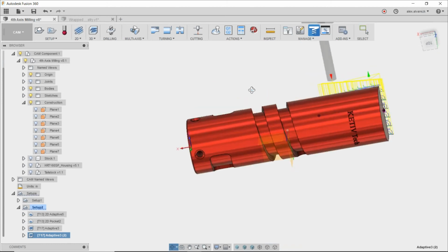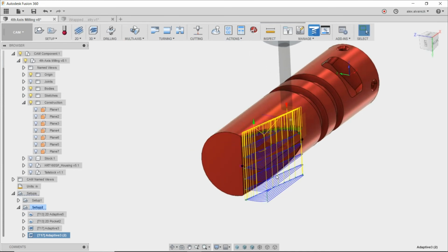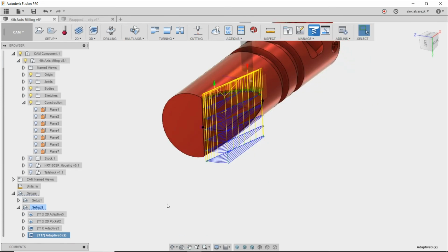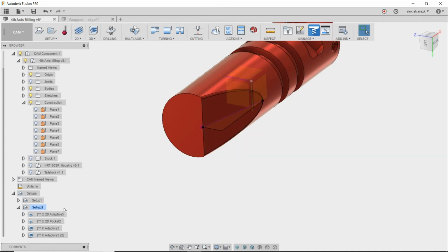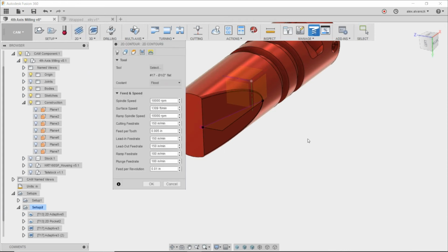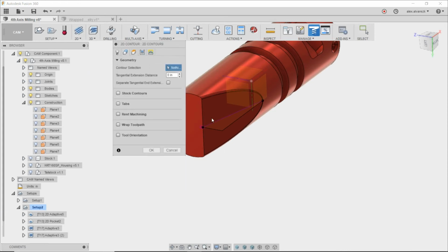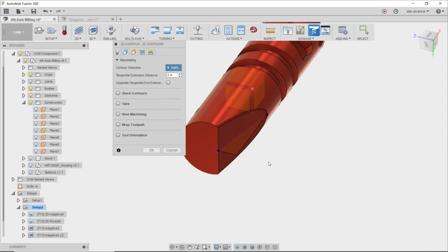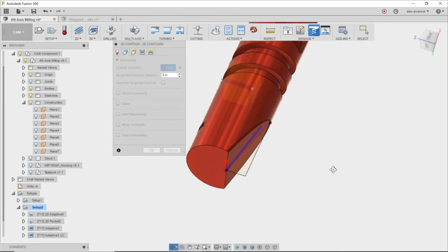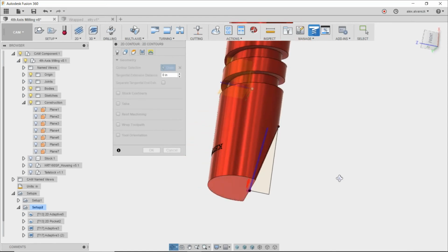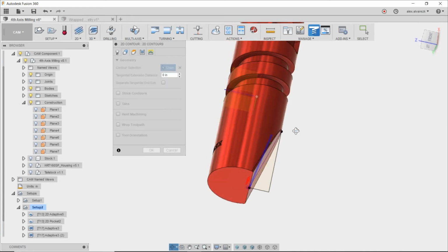So again, for this case, it is going all the way to the bottom. So now what you can do then is just have the contour just coming around here and just finishing up that face. So you can select it to the contour. Again, using that same tool, contour selection. Notice if I hover over this sketch, it highlights the entire sketch. I don't want it to do that, so by holding the Alt key, right, you move on to a single selection, right? So you see that the line isn't exactly following that path that I selected.